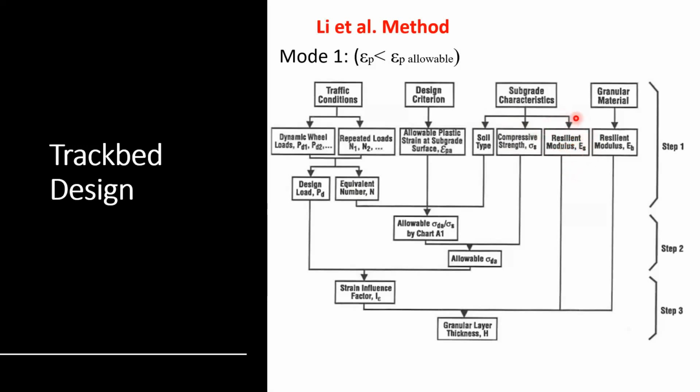But something I came across was heavy correlations between the resilient modulus and the unconfined compressive strength. And again, don't think about the unconfined compressive strength as a test exclusively for clay only. It can also be handy in intermixed soils where you have enough cohesion and consistency. So you can always rely on this when you're dealing with silt, clay, or silt-clay-like materials to get a sense of your resilient modulus.